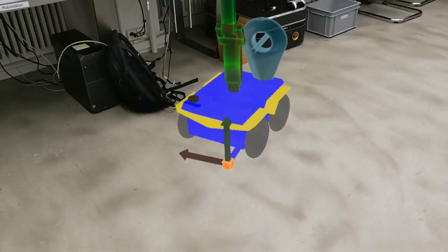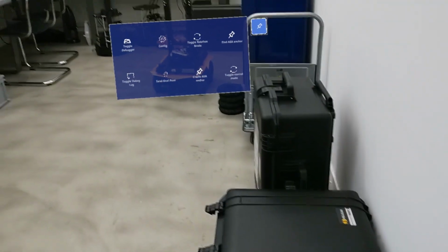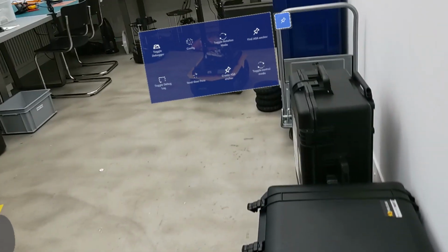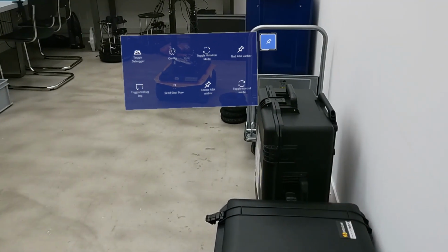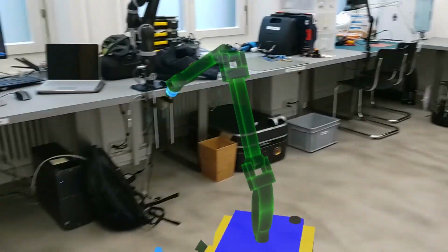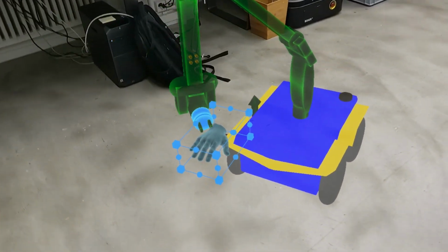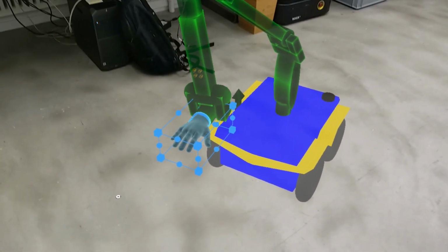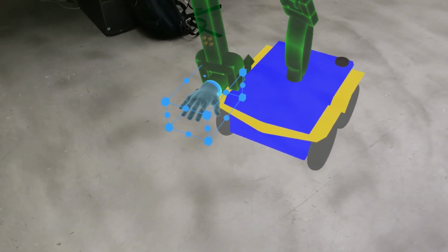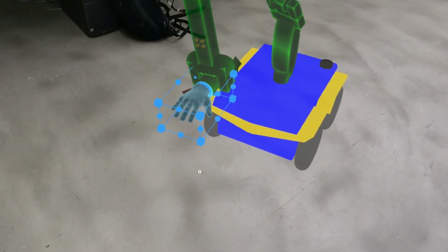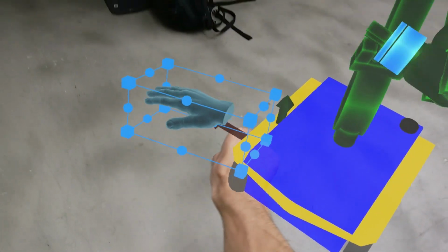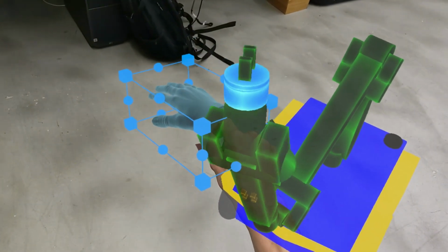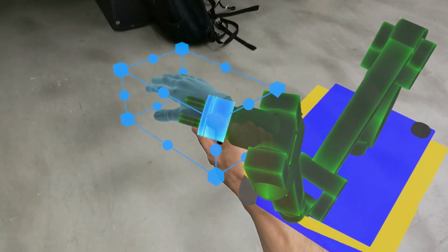Okay, we just located our anchor. By pressing the toggle control mode button, which in a very similar manner also exists in the Android app, we toggle the control mode to our new alternative and maybe also more intuitive way of controlling Jackal and the industrial robot arm. This hand model, which you can see here, is bound. The user can now grab the hand model and position its pose however the user would like, and the robotic arm will try to match its end effector with the pose of the hand.